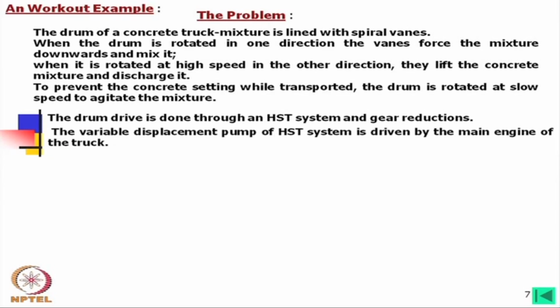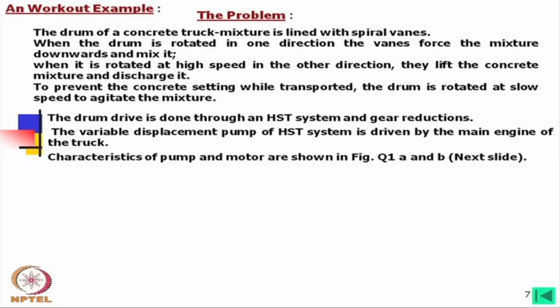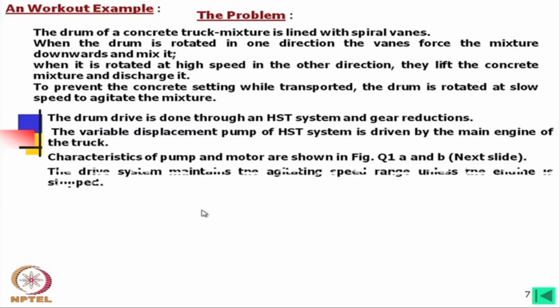The variable displacement pump of the HST system is driven by the main engine of the truck. Characteristics of pump and motor are shown in the figure. There is a figure in the next slides. Now, the drive system maintains the agitating speed range unless the engine is stopped.